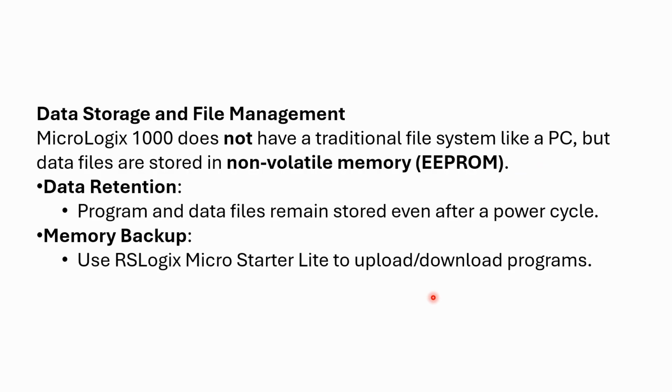Now we talk a little bit here about data storage and file management. The MicroLogix 1000 doesn't have a traditional file system like a PC would, but data files are stored in non-volatile memory. It's an EEPROM, and for data retention, the program and data files will remain stored even after a power cycle. I will say I had an issue years ago.